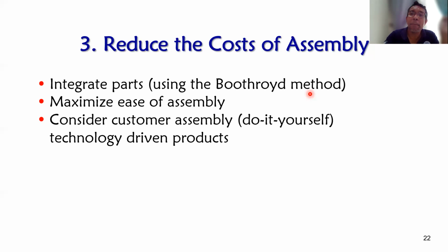And then part number two, part insertion from the top of the assemblies. This attribute of the part assembly is called Z axis. Normally when you push from the top, they use the gravity to help stabilize the part assembly. So you just leave it and then just make the part self-assemble, so they can maximize easy assembly of this part. So you need to think about that to design for the assembly part.